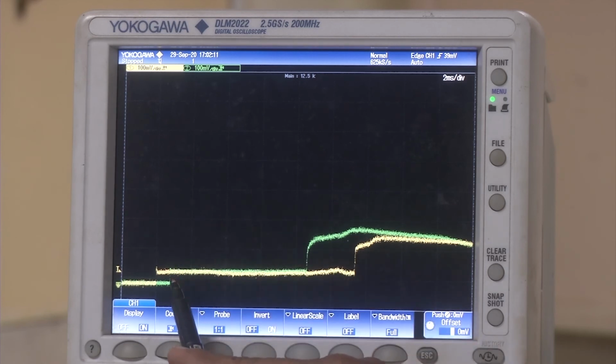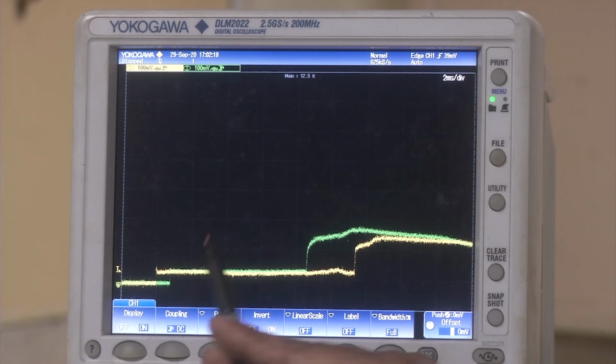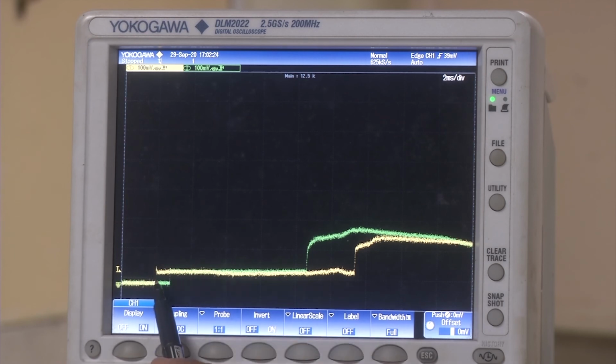the second pressure transducer is located 1335 millimeter from the end flange. That means, when the shock wave travels in the driven section of the tube, the first pressure transducer sees the flow information of the induced mass, and this jump, if you can see, is instantaneous, like a step. So, this instantaneous jump refers to the primary shock generation.